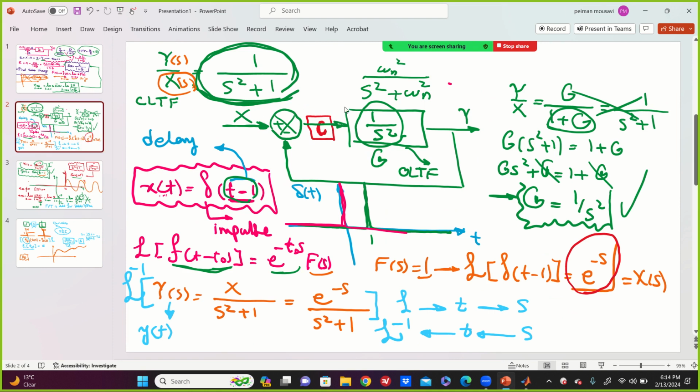Okay, okay. So, okay. Sir, feedback is for comparing the output with the input. Okay? So this has no relation with the G. G is for the closed loop transfer function. It relates the output over input, closed loop transfer function. This equals, from the previous class, open loop transfer function divided by 1 plus open loop transfer function. See what I'm saying? From here, we find open loop transfer function is 1 over s squared, put here.